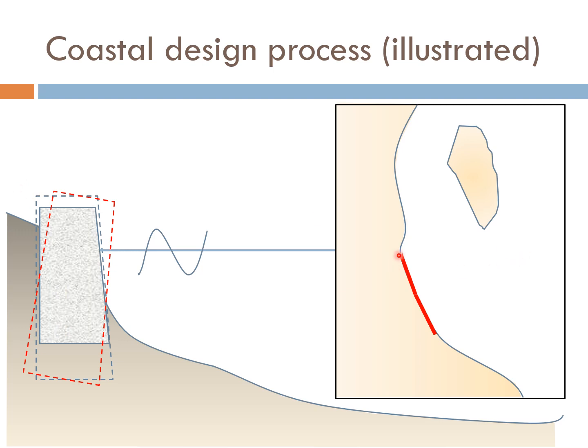So that is the functional design part, to make sure that the structure is able to protect this segment of the beach from the attack of the wave. Presumably the problem is erosion, and also it is high enough to prevent overtopping of wave, and deep enough to be stable, and also guard against any scouring or foundation failure.